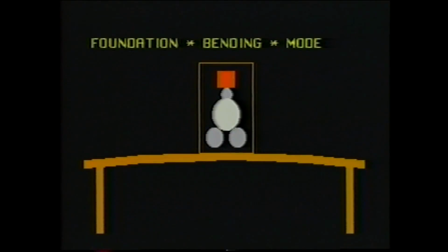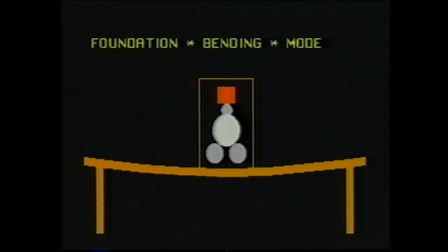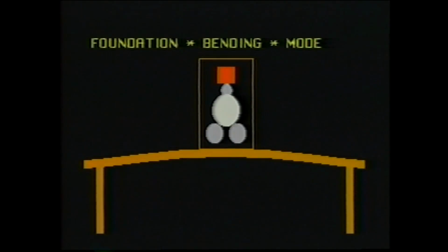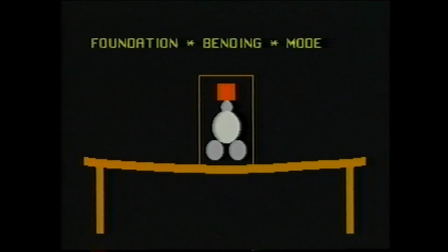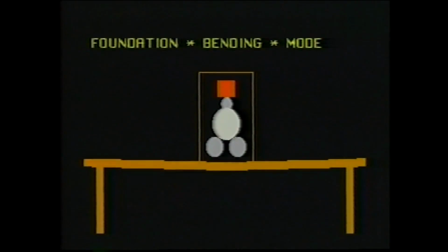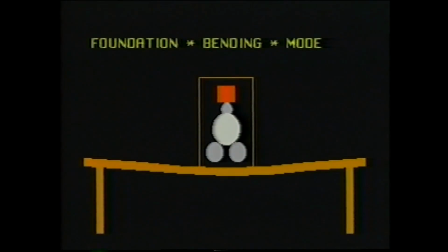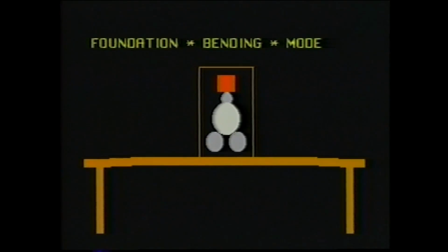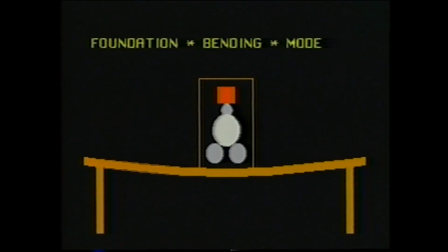This foundation may be adequate from conventional load capacity or stress-based design criteria. However, in order to achieve acceptable machine stability, winder foundation design must be based on dynamic considerations as well as static strength. This requires either very conservative design or the application of finite element modeling to determine foundation geometry.